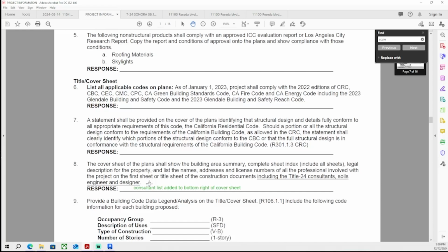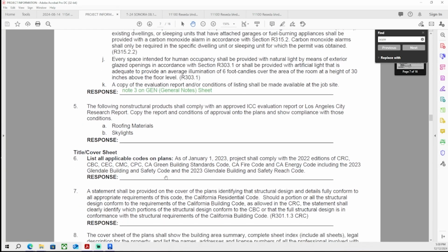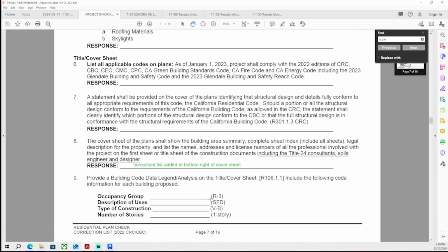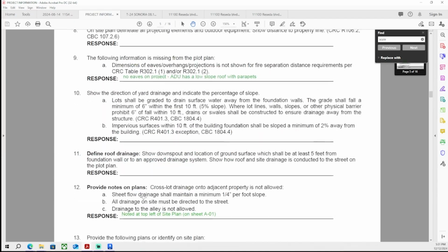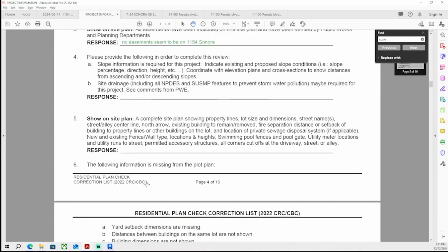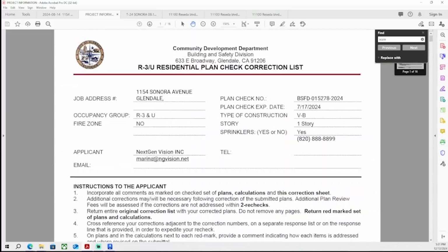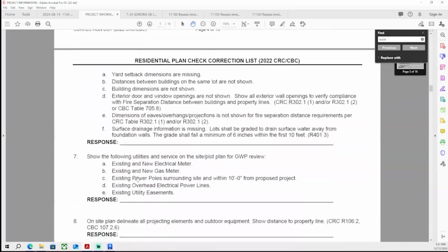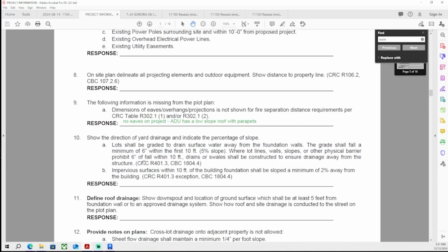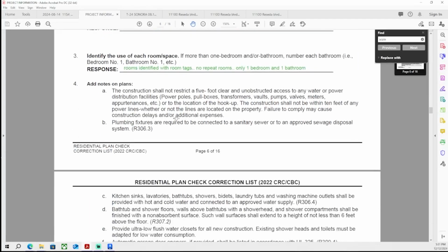You know, you can have the accordion wall that slides all the way through. That's fine. But once you need that fire rated construction, your window openings are limited to 25% of that wall. But that's just for a regular fire rated wall. If it's a fire rated wall that is on the property line or very close to the property line, then it's like no openings. But if you need a fire rated wall that's say like 4 feet from a property line or 5 feet from a property line or something like that, then you could have, I believe it's up to 25% of it being window.